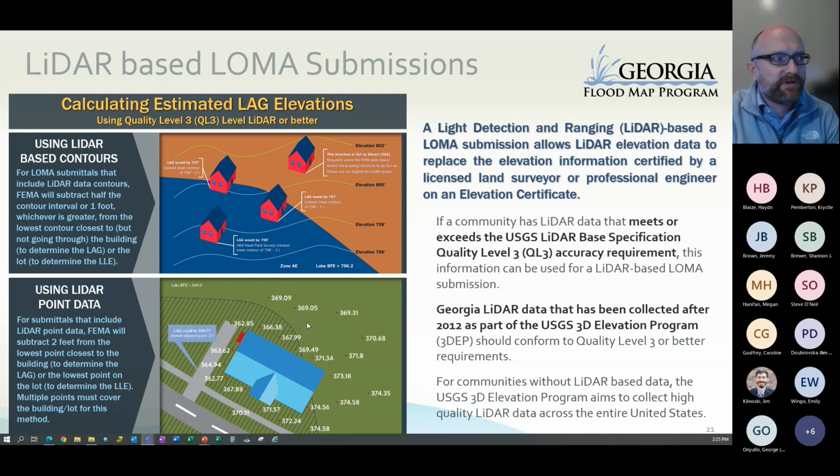enforce a buffer requirement depending on whether you're using contours to get that LAG or whether you're using raw LiDAR LAS points to get that LAG. And that's just a way of acknowledging that while LiDAR is highly accurate, it's still not quite to the same standard as a survey. Survey would traditionally be used for those LAG elevations. And so we have a secondary report on the BLE dashboard where we're using this contour-based method to enforce a buffer and extract out LAGs for properties.